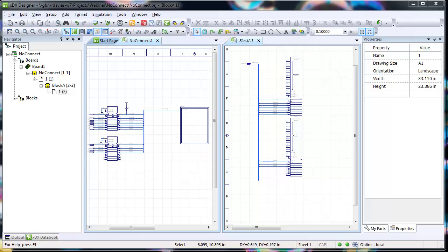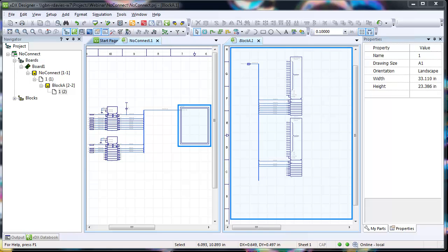No-connect symbols are used to terminate unconnected pins on components so that they are ignored by design rule checks DRC107 and DRC123. In addition, the symbols prevent the attached nets being reported as single-pin nets by the packager or PCB netlist utilities.